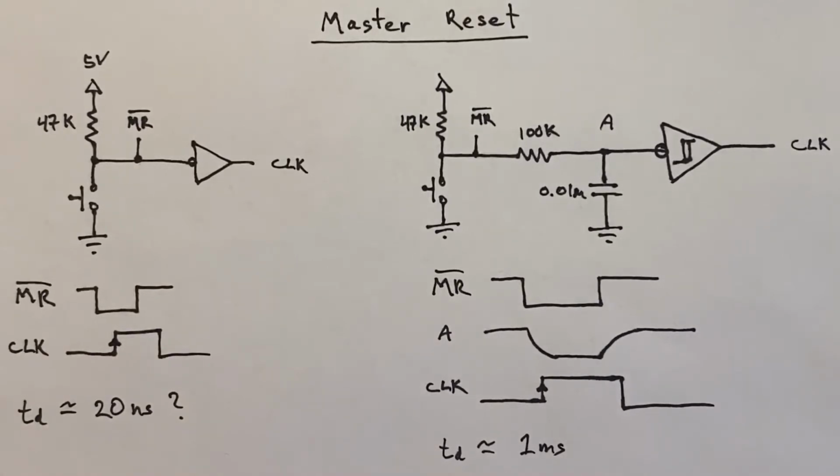So it's an incredibly short time, but you still got to satisfy it. It's called the setup time. Otherwise, your counter can get unstable and start oscillating back and forth and have that metastable state, which we talked about earlier with a slow rising clock pulse.